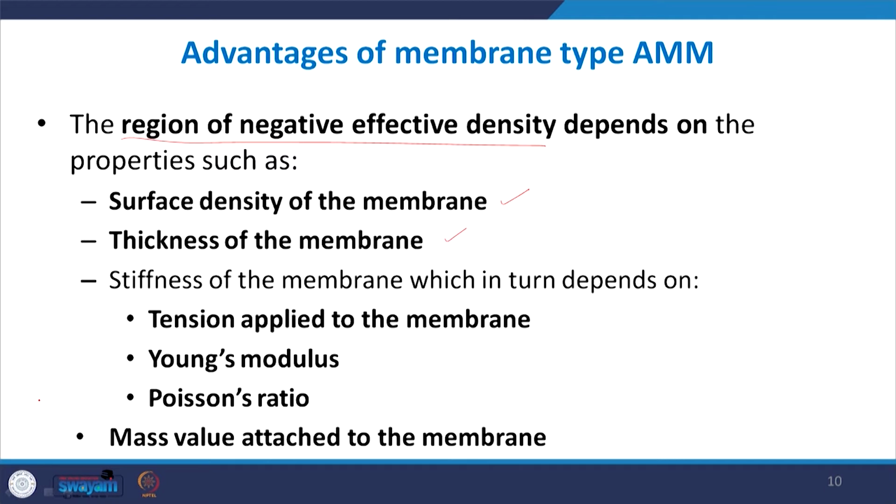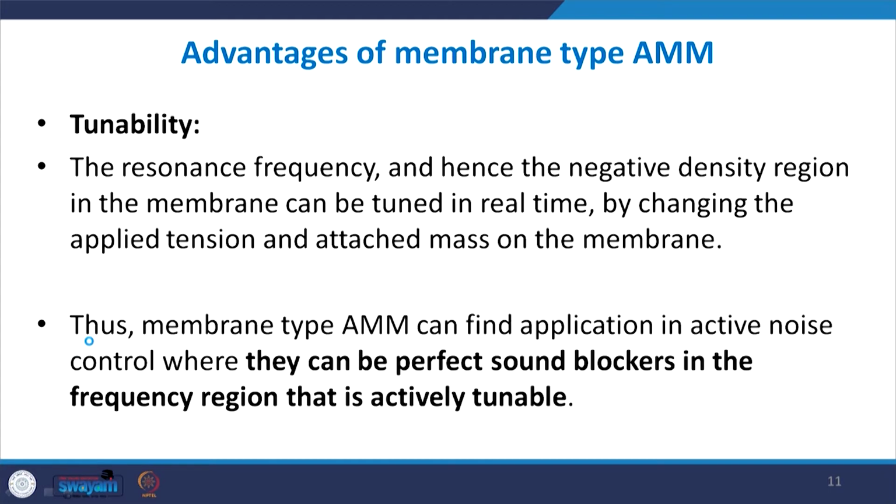So, what you see here, this is the third quantity, which is the mass value which is being attached to the membrane. So, these are the various parameters that are used to govern the response of such structures, and as you can see, this is one of the external parameters which is not intrinsic to the membrane construction. So, that is why they offer something called tunability. Tunability is the characteristic where you can tune the response of a structure in real time based on what is the incoming noise.